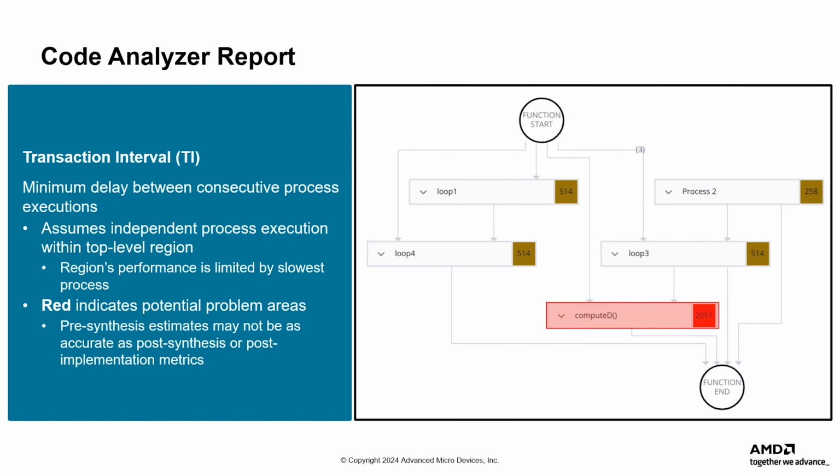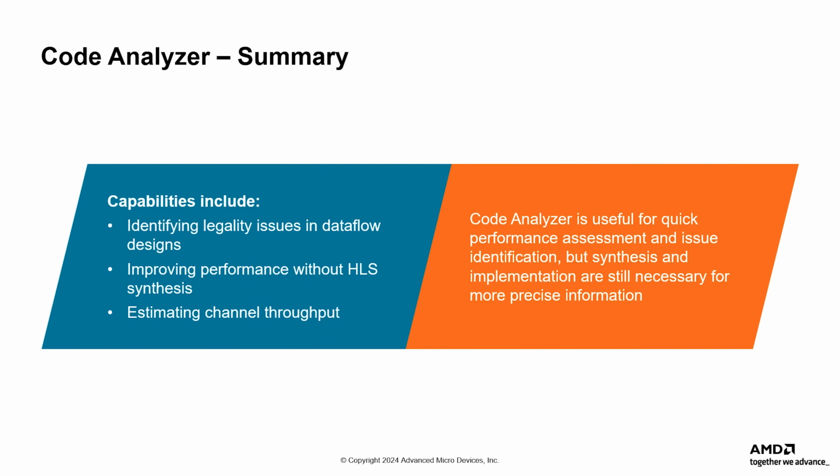However, note that the pre-synthesis estimates used in the graph do not offer the same fidelity as the post-synthesis or post-implementation metrics. Code Analyzer can help identify legality issues in data flow designs, improve performance without requiring HLS synthesis, and provide estimates of channel throughput. In summary, Code Analyzer is a valuable tool for quickly assessing performance potential, identifying problems, and resolving them. However, for situations that demand more precise information, synthesis and implementation should be employed.